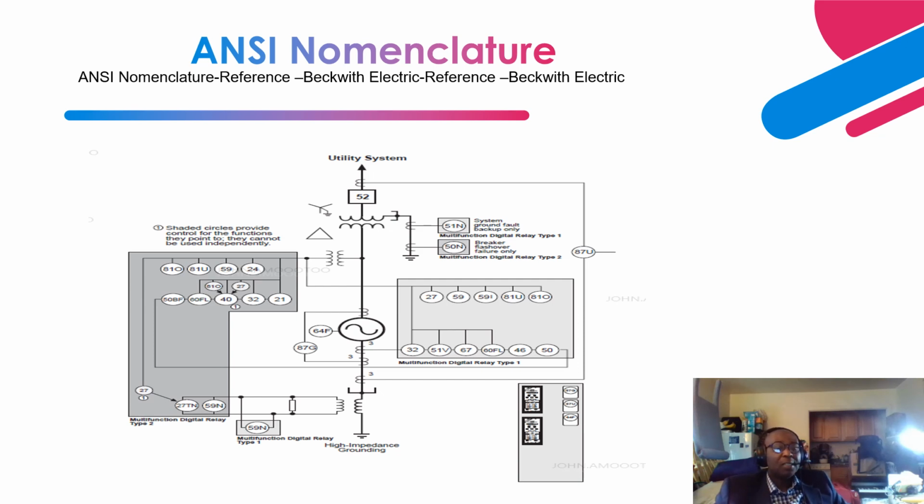This is the generator step-up transformer. This is what steps the voltage from the terminal voltage of the generator to a higher voltage. Let's say you have a typical generator with an output voltage of 30.8 kV, and you step it up to 230 kV or 345 kV. This is implemented by the generator step-up transformer. It steps the voltage up from 30.8 kV to 230 kV or 345 kV based on the desired voltage you need on the transmission end.